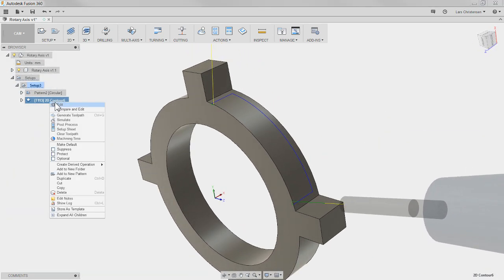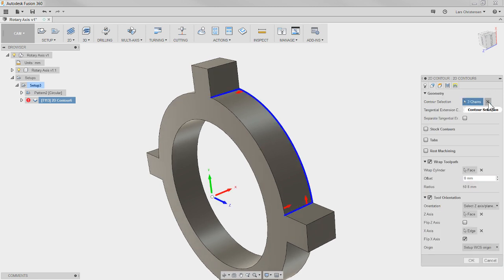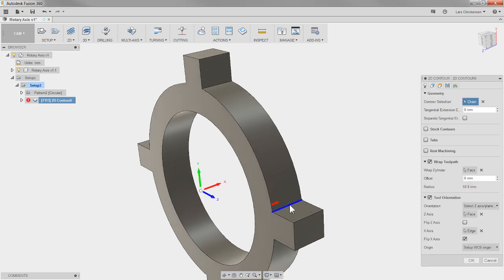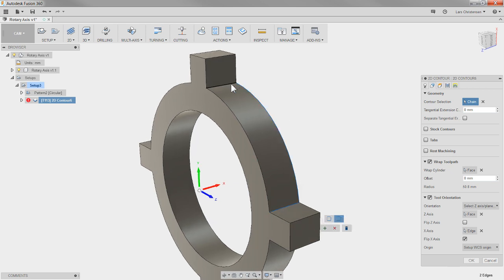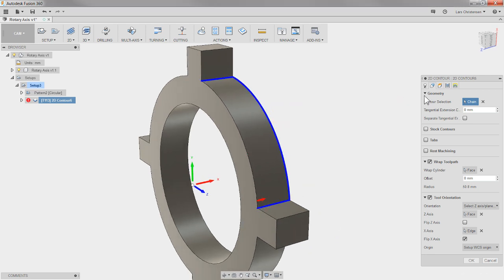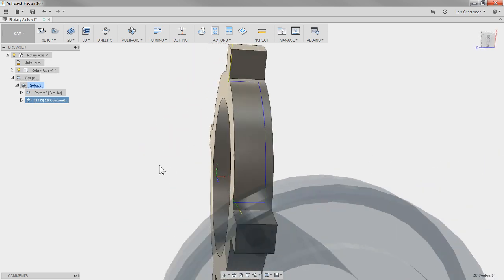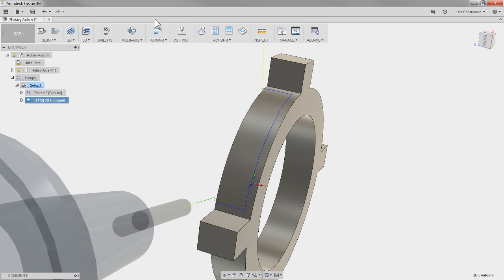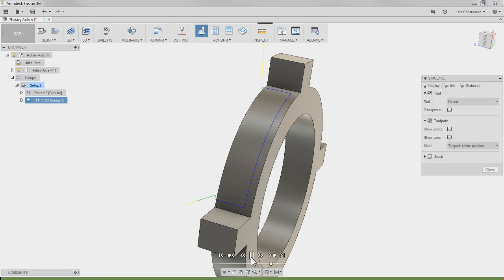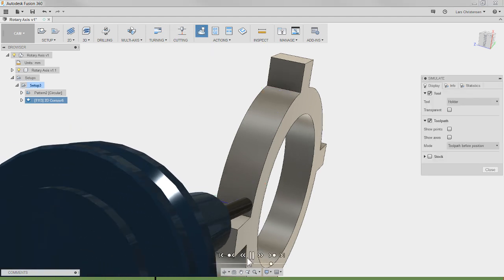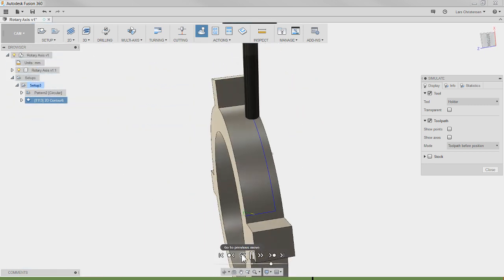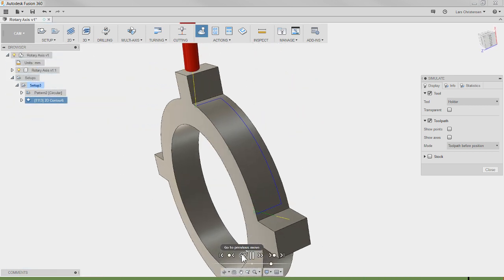Well, what I did in the second round was, let me just select one edge. I'm going to go in and select it again, and then I can select open contour. Now I have this open contour again, and I can select the remaining 2 edges. Same result. One chain, just an opening here. And so now you will see when the toolpath comes in, it's going to come in from the side and machine up like this here. Okay?